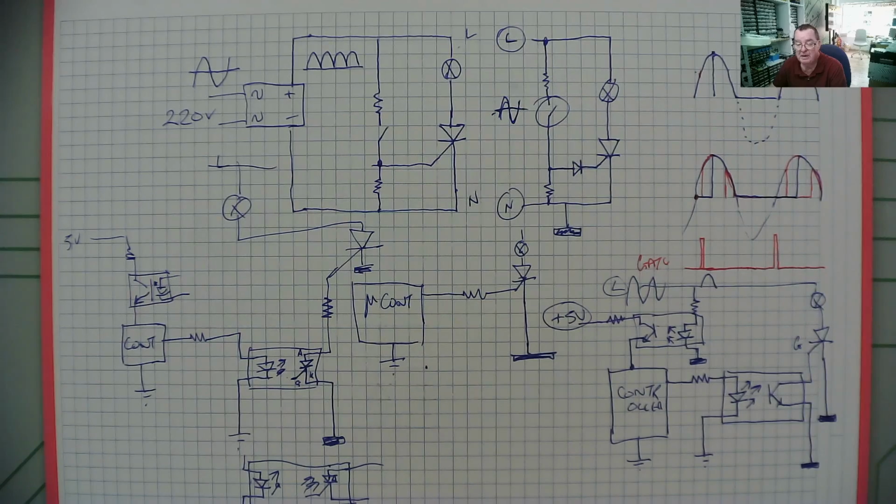And the main thing you need to consider is, if a thyristor or triac goes short, almost certainly it's because whatever load is attached to it, whatever it is switching, was also short. Therefore, it switched on, feeding into a short, it passed too much current, and it went blue, yeah? Sometimes they can actually explode, in which case they are definitely open circuit. That is basically what you find with thyristors.